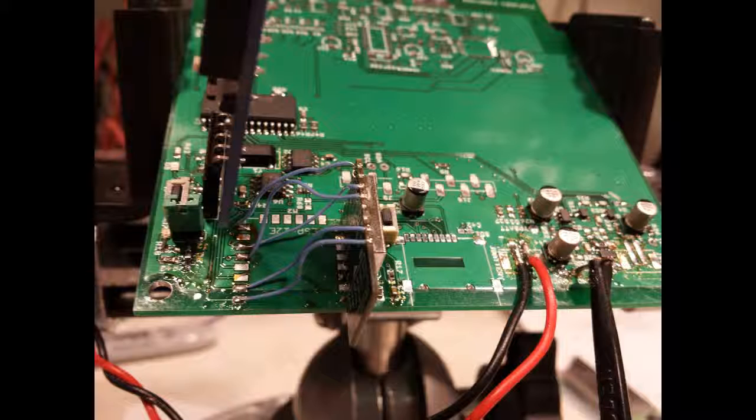I ended up taking off almost all the ICs, and then I ended up taking this radio on and off about 4 or 5 times. And I eventually got it to work off the board, and then I slowly put it back on by making single wire connections and figured out that it was a power supply issue. Pulled that tantalum cap off and we're good to go. Then I ended up putting everything back on the board.